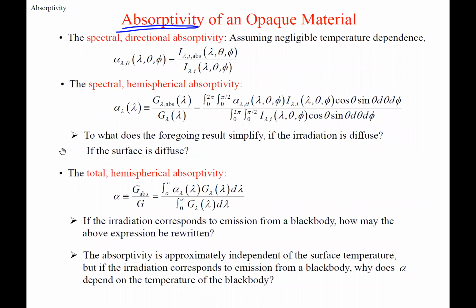With absorptivity, we can look at it just like we did with these equations for emissivity. We have what's coming in, we have our perfect absorber, and we have directional and spectral. With direction, we have influence, and with wavelength, we have our influence. If we integrate over direction, we just have spectral, so then we just have wavelengths.